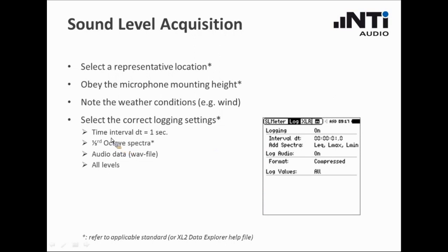We have to set the timing interval to 1 second, the logging interval. We should record the third octave spectra. Here, this depends a little bit also on the national standard. Some national standards only require the LEq, some others, in addition, the maximum and the minimum level of spectra.